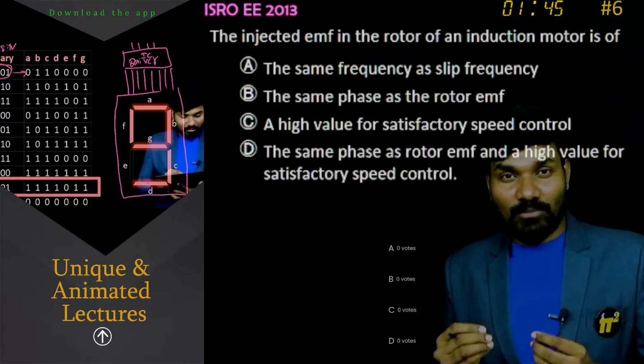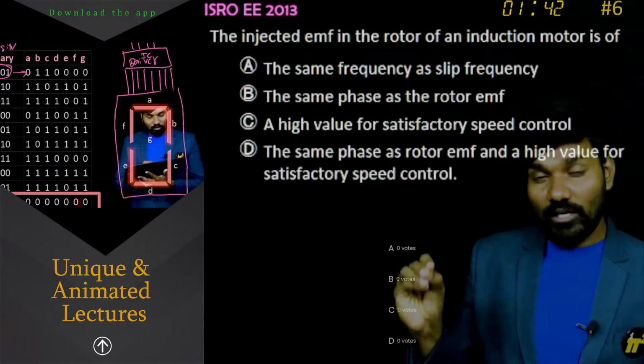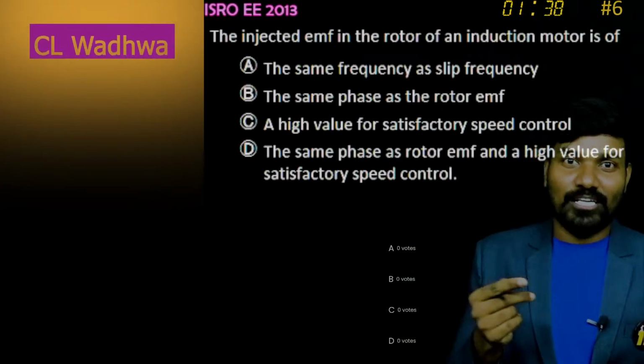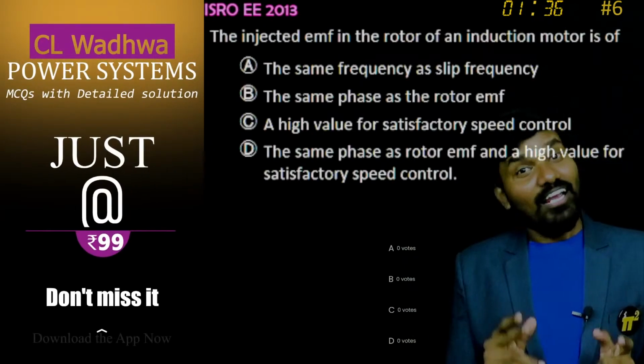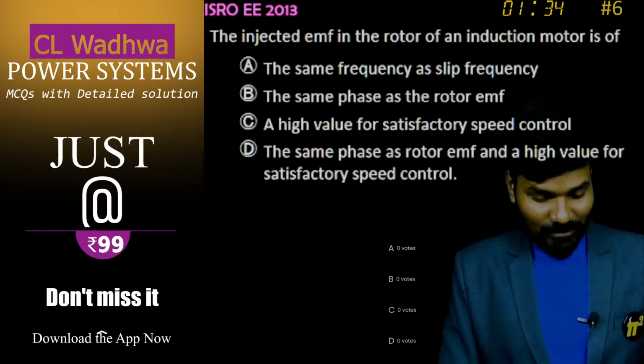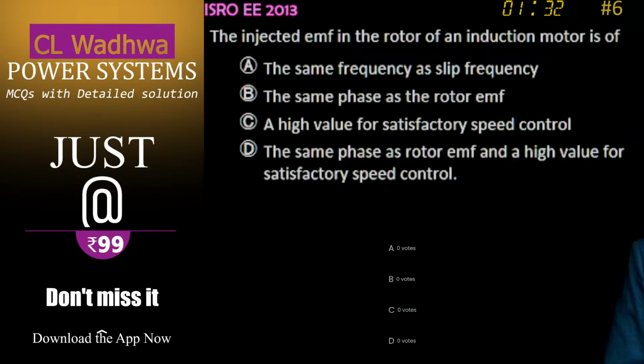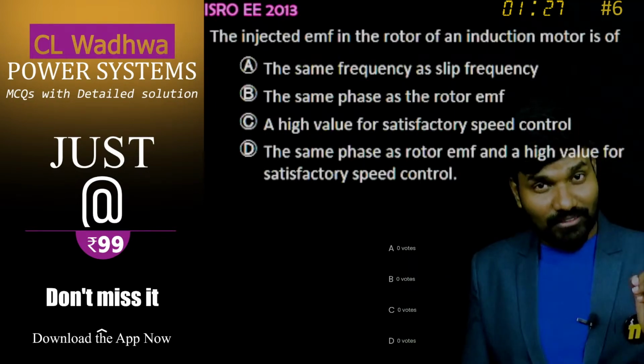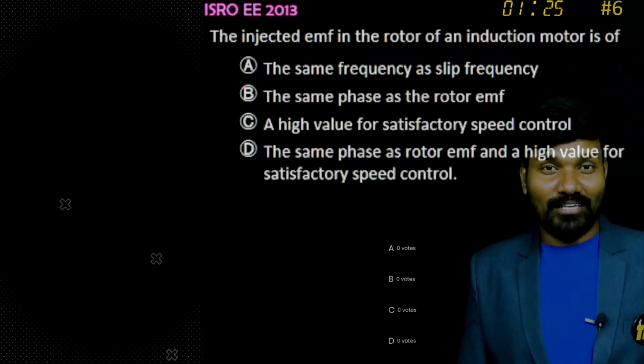In a transformer, oil is used for cooling purpose also, not just insulation. Mainly, I would say cooling is a key aspect there, alongside the insulation. Anyways, that could be an interesting question. Air versus transformer oil, which one has good dielectric strength? Because this was one of the BARC interview questions.